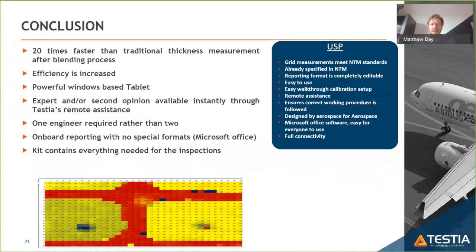So the operator must follow the calibration process on the calibrated step blocks. They must do this every time, so that ensures that the operator or the owner of the aircraft is confident that the process has been done every single time and it is done correctly.